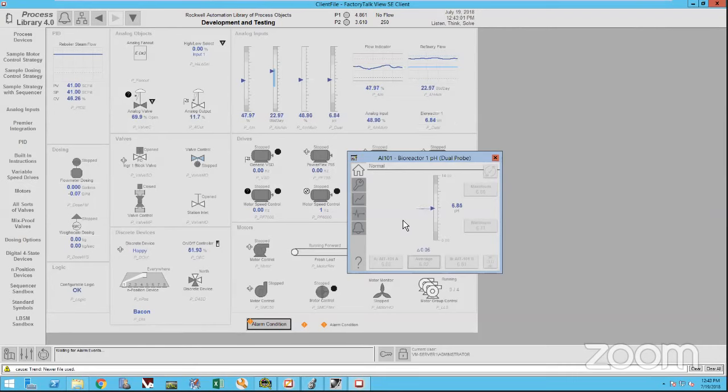What you'll see here, as I mentioned, so I just opened this guy up. I'm now getting a little trace line. So as my value in analog goes up and down, if I have that open, I'm now seeing what that variation is. The different shading of gray here are my deadbands for my alarm. As soon as that alarm hits one of those shaded deadbands, I now go into alarm, that changes color to yellow or red based on my severity level that I assign. I now get an alarm, I can acknowledge back to the controller, it's in a handshake back and forth.